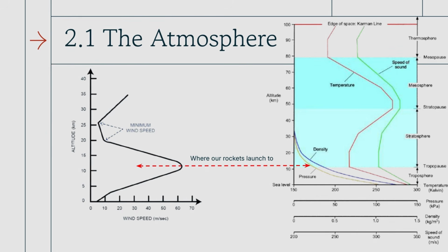So just some pictures now of what I was describing. The speed of sound and temperature, you can see the density and pressure functions. So the density and pressure drop off nearly exponentially as a function of altitude. So basically, by the time we make it to about 40,000 feet, there's not much left. So, from a drag standpoint, a lot less drag because the atmosphere is less dense.